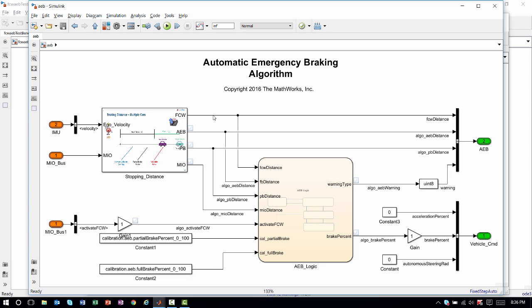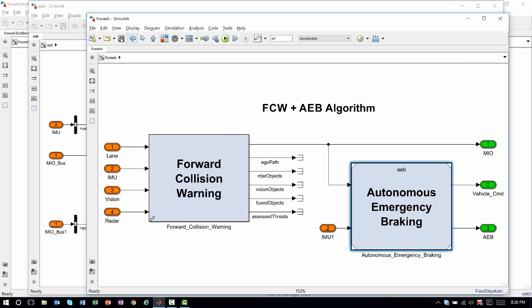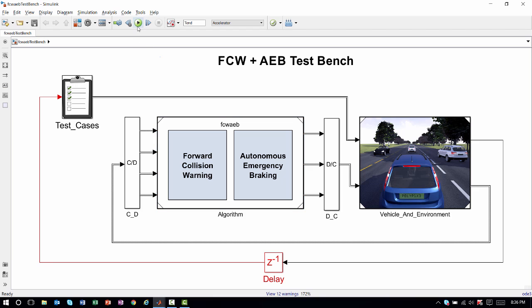And enabling it is straightforward. You go to a signal, you right-click, and say Stream Signal. Once you do that, every time you hit play in Simulink, a new test run shows up with all the signals. Very handy. Okay, so now let's run the simulation.